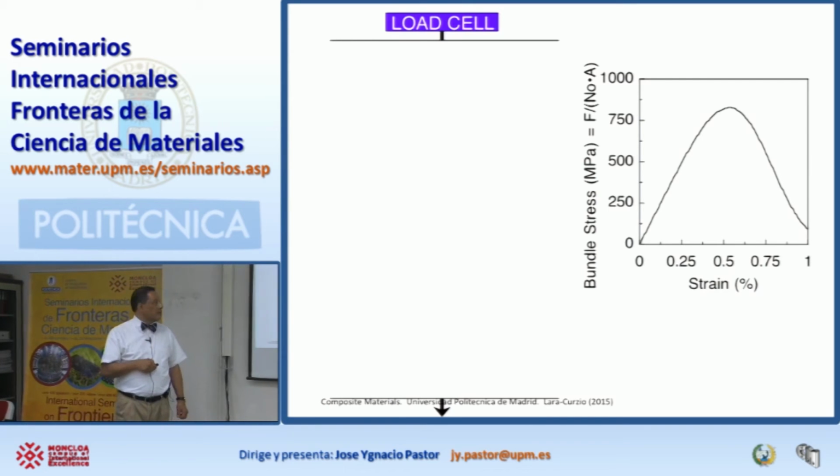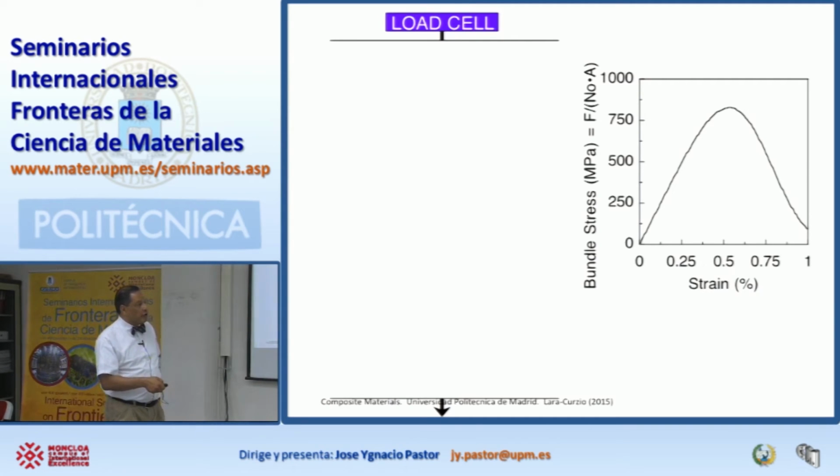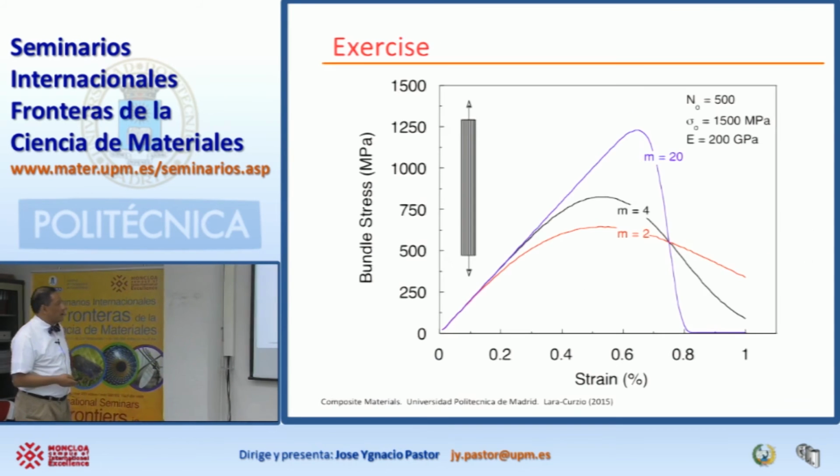Okay? These are individual fibers being stretched. Each fiber follows a stress-strain curve that looks like that, just a straight line. The beauty of this is that the collective behavior that you have from a bundle of fibers resembles the behavior of a metal. Now, the question that I had for you was, do you want a high Weibull modulus or a low one? And you guys said low.